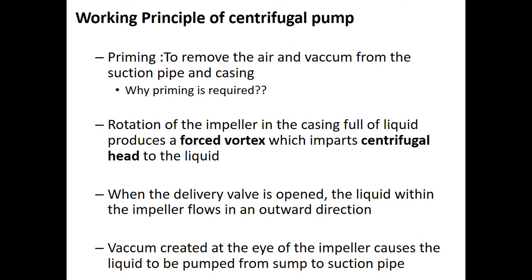So the rotation of the impeller in the casing, which is full of liquid, produces a forced vortex, which imparts a centrifugal head to the liquid or increases the pressure energy of the liquid in the impeller.